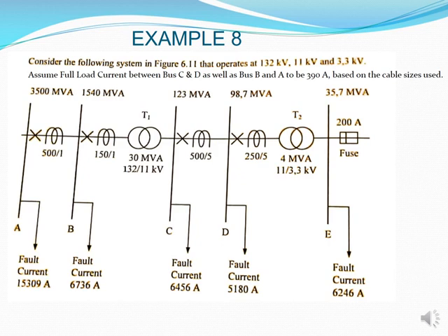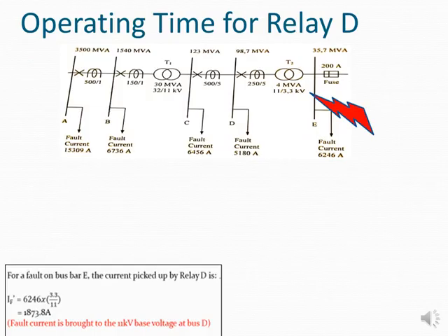They tell you that where you don't have transformers, in those portions of your network sections, you've got 390 amps as your cable size. So that is really going to be the load that you get in there. We are not given anything that talks to our overload scenario, so we will utilize our full load current in all our calculations in this case.